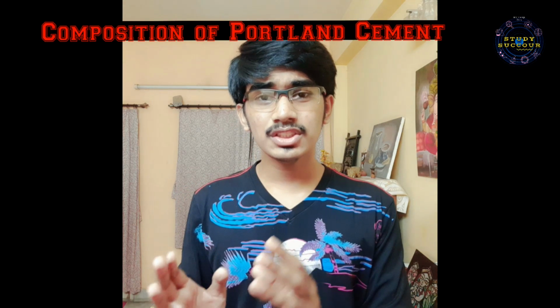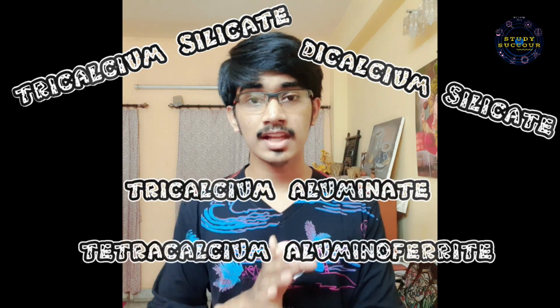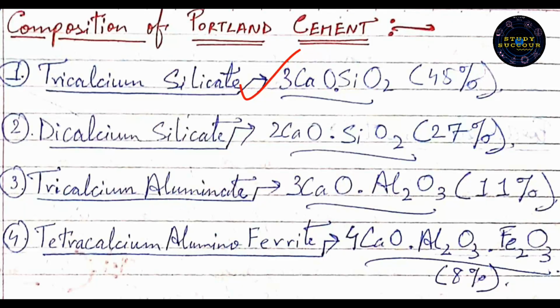If we talk about the composition of Portland cement, then Portland cement is composed of 4 different compounds, which are tricalcium silicate, dicalcium silicate, tricalcium aluminate, and tetracalcium aluminoferrite, whose chemical formulas are 3CaO.SiO2, 2CaO.SiO2, 3CaO.Al2O3 and 4CaO.Al2O3.Fe2O3. So, Portland cement is composed of 45% tricalcium silicate, 27% dicalcium silicate, 11% tricalcium aluminate and 8% tetracalcium aluminoferrite.